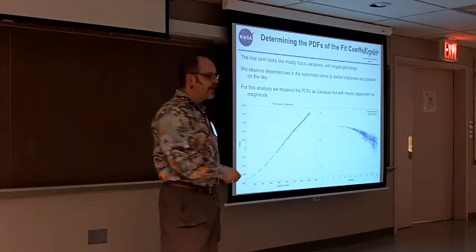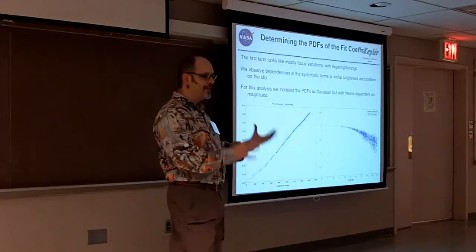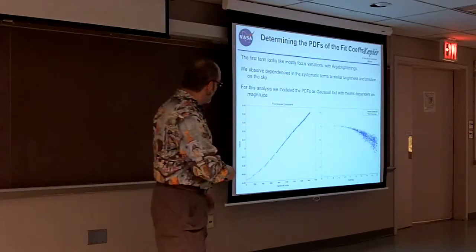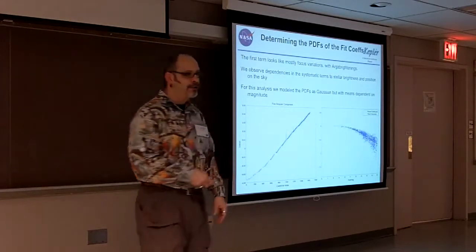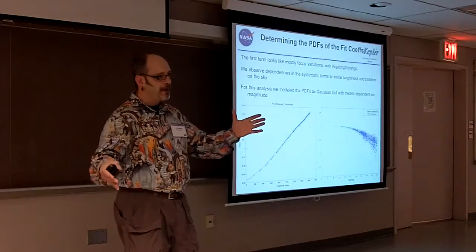This 5-degree change in temperature on a box on the outside of the spacecraft, which is supposed to be thermally isolated from the telescope, is causing approximately a 1 micron change in the distance between the CCD detectors and the primary mirror.